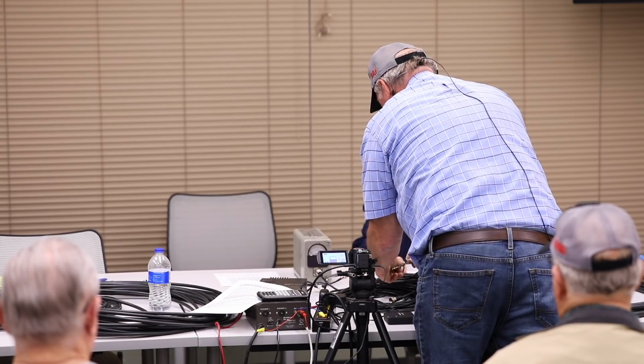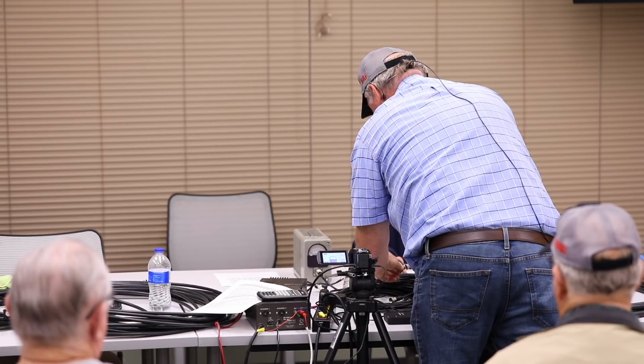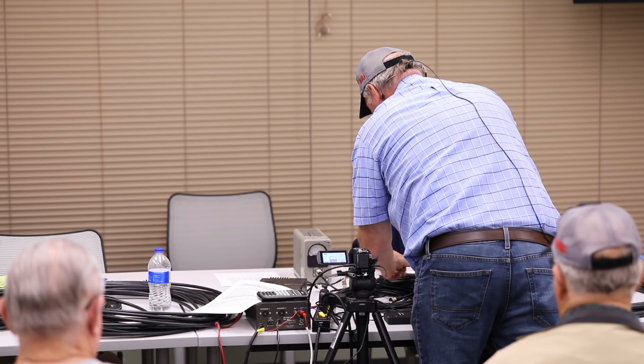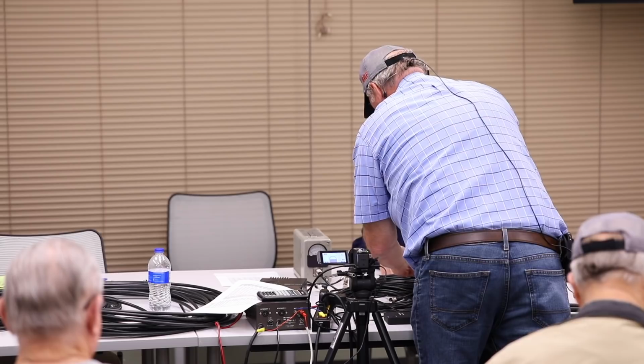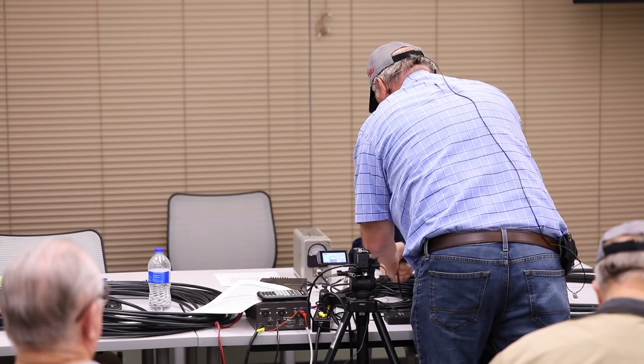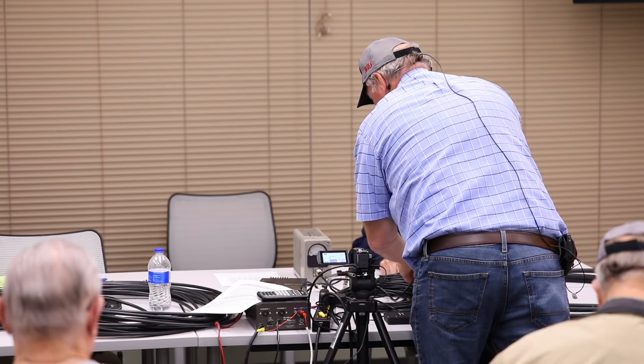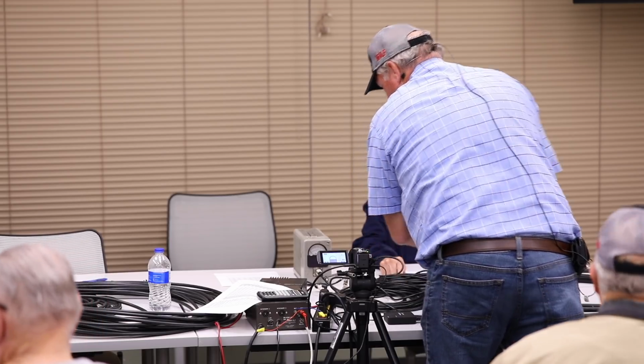And by the way, RG8X has another number for it. It's more expensive, a better cable, and I think it's called LMR 240. That stuff's expensive, but you look on the chart, you'll see that the loss on that is not much better than this. So we have our reference.